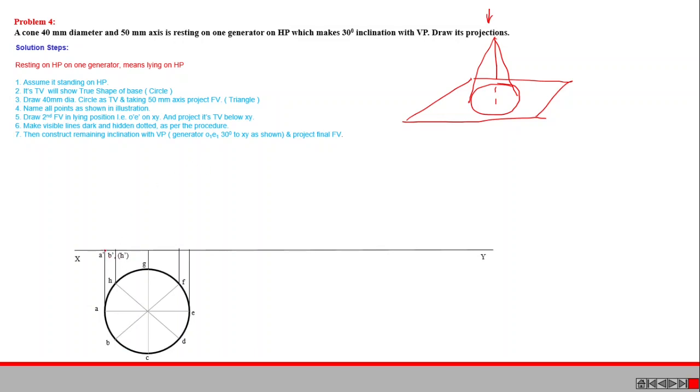because in this particular view, in the front view, we must draw this projection line here also. Then in the front view, point B is visible and H invisible. That means B dash is out of bracket and H dash must be in bracket. Similarly, that point is C dash. Then P dash is the axis point and G dash is in bracket.